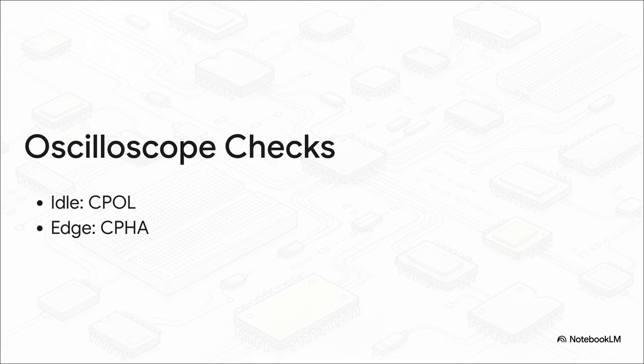Then you look at the MOSI line and see whether the data voltage stabilizes perfectly aligned with the first edge of the clock pulse or the second edge. That instantly reveals your clock phase. It's a fantastic troubleshooting step to help you quickly identify clock phase errors and fix your firmware's register settings.